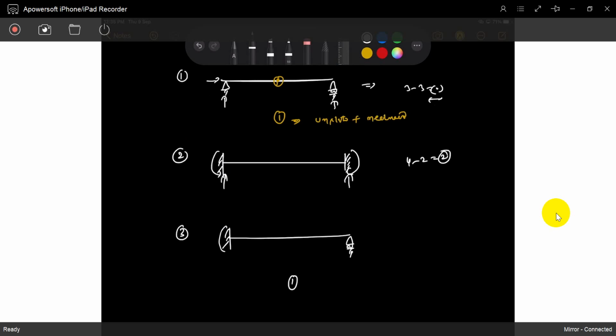The maximum moment is here. If you apply any load, the moment reaching this position is higher. It will reach MP first. When it is reaching the MP, this point is converted to a hinge. Initially it is a fixed support. When you apply the load, the moment at that location reaches MP, and it resists the MP moment. But if we keep loading, it gives the MP moment in return and converts to a hinge. So now it is a hinge.